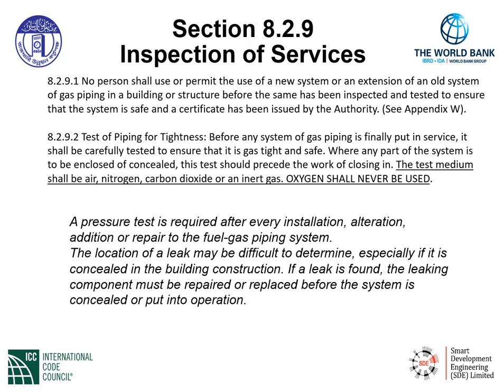Where any part of the system is to be enclosed or concealed, the test should be done prior to the work of closing in. So what we're saying here is we need to test segments of the gas piping system that are going to be either enclosed or concealed prior to concealing it in the construction. So as inspectors, we may have to be called out and look at the testing to be done and looking at the proper materials and fittings that make up the part of the system that will be concealed prior to building construction around that.